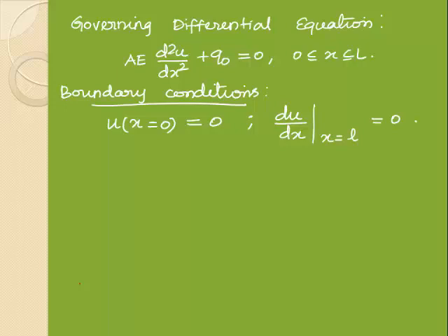Okay, so after finding the suitable trial function satisfying the boundary conditions, we have to substitute the trial function into the given governing differential equation of the structure, and by equating those two we will get the residual value. Then the residual should be equal to 0 to get the required answers. Following that, different types of weighted residual approaches are there. In each approach, the residual will be equal to 0 subject to certain conditions. So let us discuss in this lecture video the standard procedure of weighted residual approach.